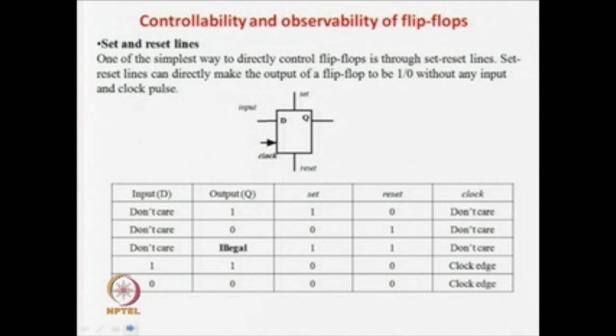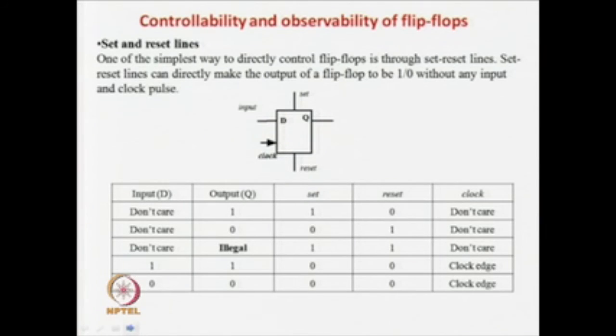So, how to do that? One major problem we have seen in the last lecture was to control the output of the flip flops, which are nothing but your secondary inputs. So, how can you do that? One very simple way: as we already discussed in our lectures, we will be using D flip flops as they are standard used in all VLSI circuits.